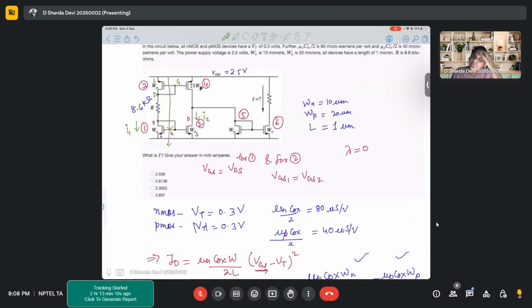In that lecture he just told we have the diode connected, and below we will connect one resistor, and using that resistor we can control the GM of all the MOSFETs, and he called it a GM biased current mirror.